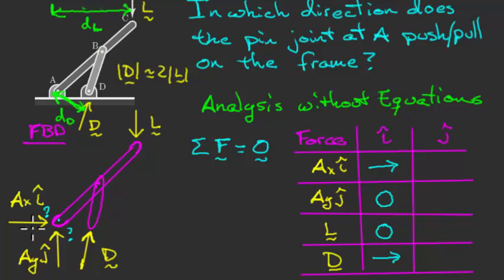Wow, another mistake I made initially. So AX, let's just write this down. It must go the other way for equilibrium. So it must go to the left. And therefore, on my free body diagram, let me just erase this question mark, erase that arrow there. On my free body diagram, let me draw it correctly. This force has to be going to the left. Right? To the left. That's exactly the way it must go. Cool. Now let's go to the vertical pieces.